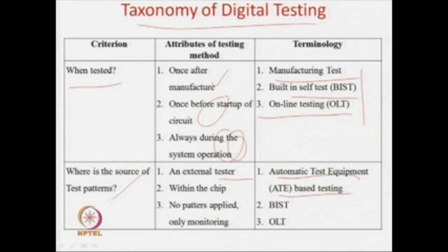Now in a BIST, what is a BIST? BIST is built-in self-test. In this case, the circuit is starting its operation, and before that we apply some test patterns and get a response. If I have manufactured a circuit and put it in your laptop, obviously you cannot bring the ATE machine and test your circuit. So, in that case, the test pattern generator and the response analyzer are within your circuit. We will slowly see towards the end of the course how it is done.